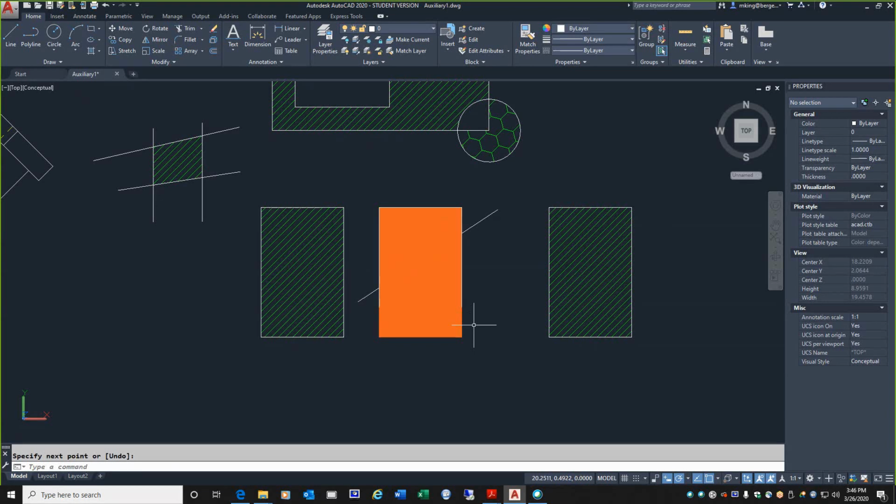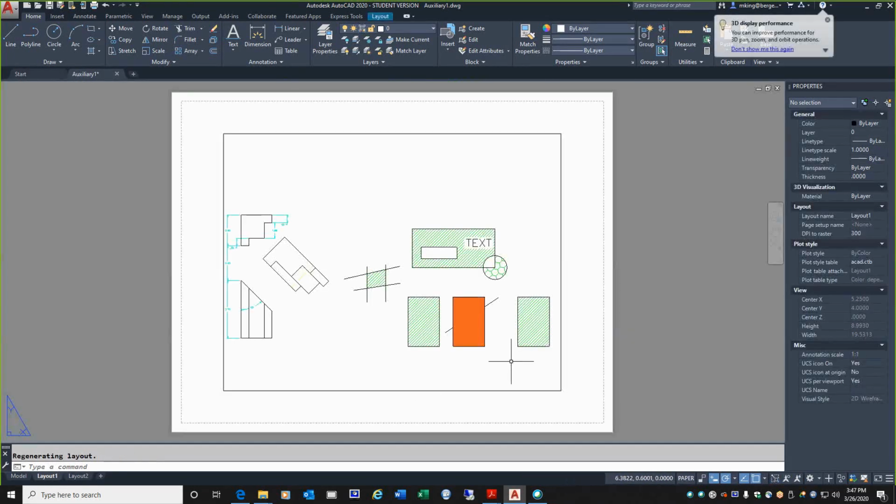Now, challenge number 2 is an easy trap to fall into. We are looking at a black background. But when you create your drawing and you print it or present it, it's going to be in layout space, which will be a white background. So really, all of these white lines are black, and the background, which is black, is white, and the color scheme that you think looks great in model space might look bad in layout space. So what you need to do is constantly switch to layout and see how it looks in there.